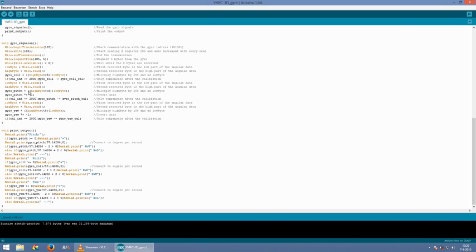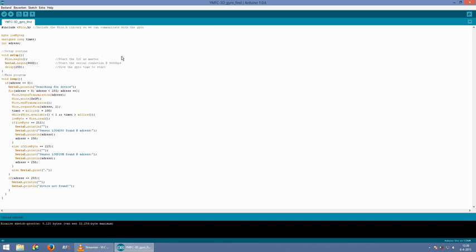If the directions of your gyro don't correspond to the serial output, you can change their direction by multiplying the angular rate by 1 or -1. If your gyro is not responding to the program, or you use the L3GD20, it is possible that the gyro's address in the program is incorrect.